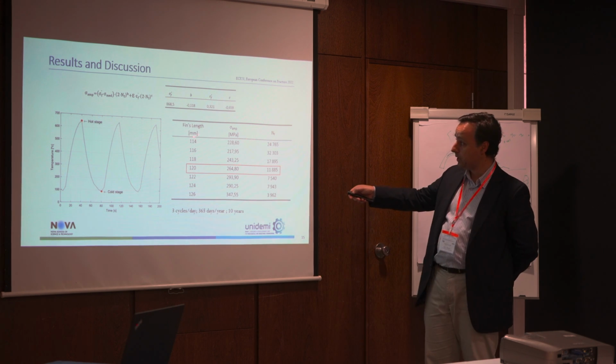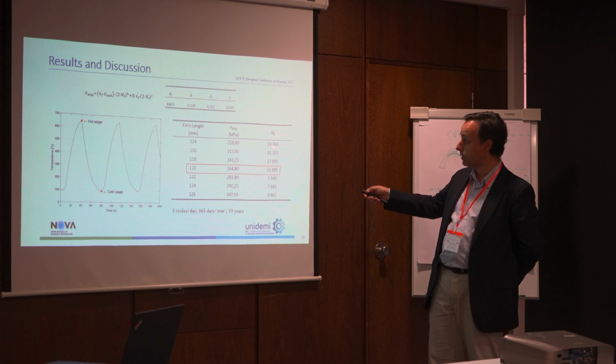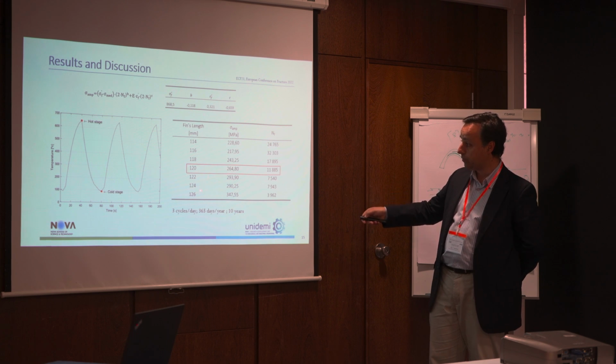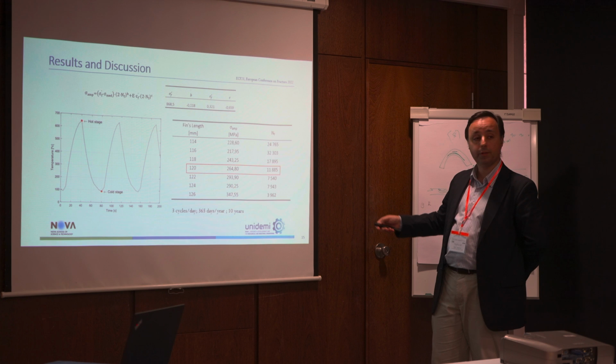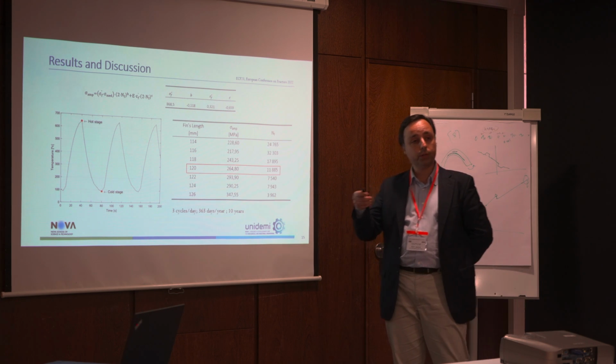So you can see that for the fins with shorter lengths, the amplitude stresses are lower, the mean stresses are lower, so the fatigue life is higher, and for higher fin length, we will have lower fatigue lives.